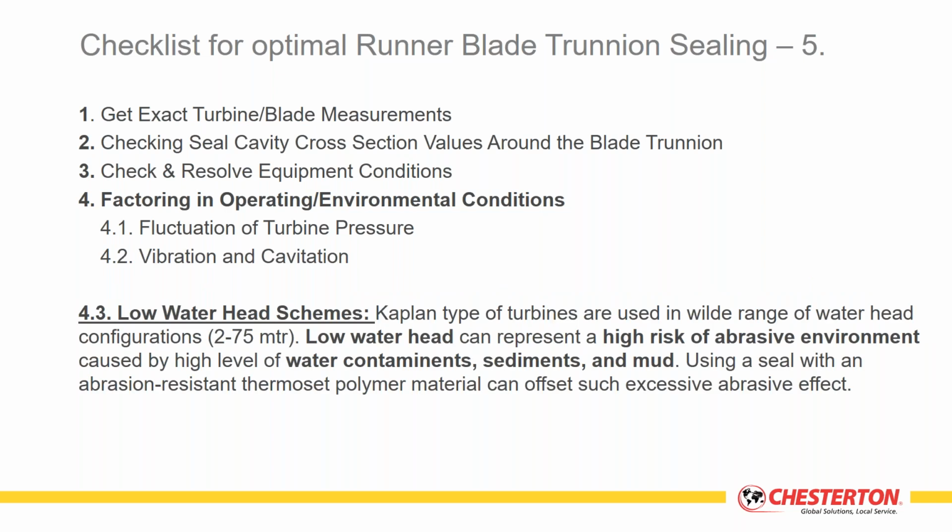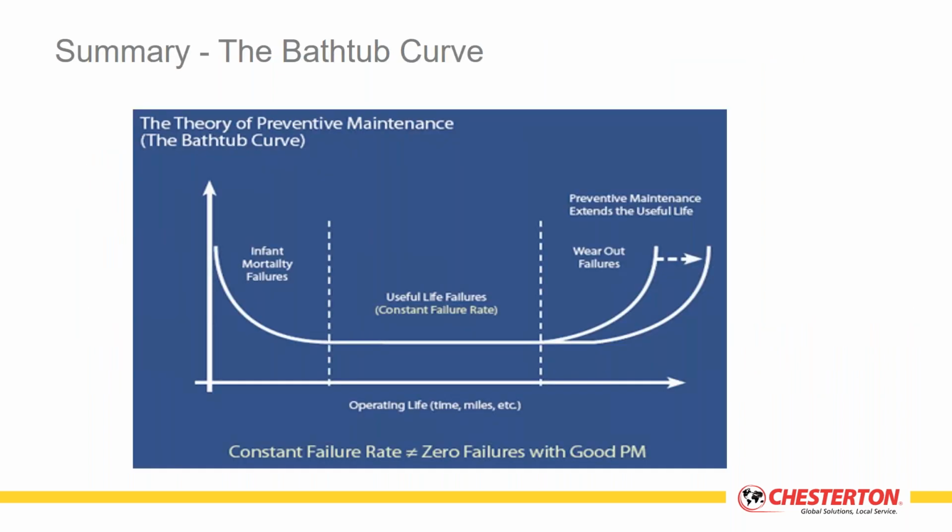Low water head: this is what I mentioned before, that especially in the low water head, there is a very high risk of abrasive contamination of the water just by the sediments, like the mud, and this has a high wear on the seals.